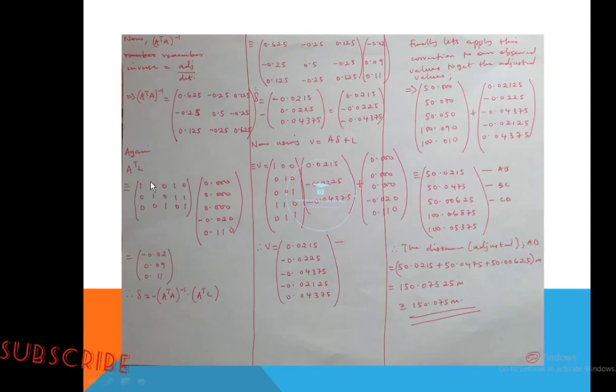Now the next part of the formula for D, which is the correction to the approximate parameters, is that we are going to also have A transpose L, right? We already have our A transpose, and then we also have our L. So the next thing is we are going to multiply these two matrices. By the time we multiply these two matrices, we have a 3 by 1 matrix, right? So the 3 by 1 matrix is minus 0.02, then 0.09, and then 0.11. So this is now the product of these two matrices.